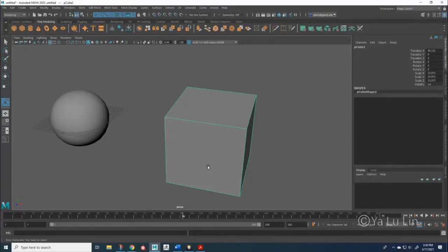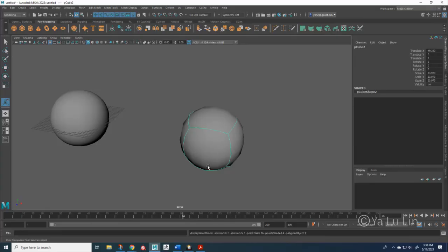This is the preview part. So I can press hotkey 3. The hotkey 3 doesn't necessarily smooth it yet. It just gives you a preview, some basic idea what it will look like. You still look like number 1 mode. Your actual form is at this low poly form. And then number 2 is your low poly form with smooth preview. Number 3 is the actual smooth preview.